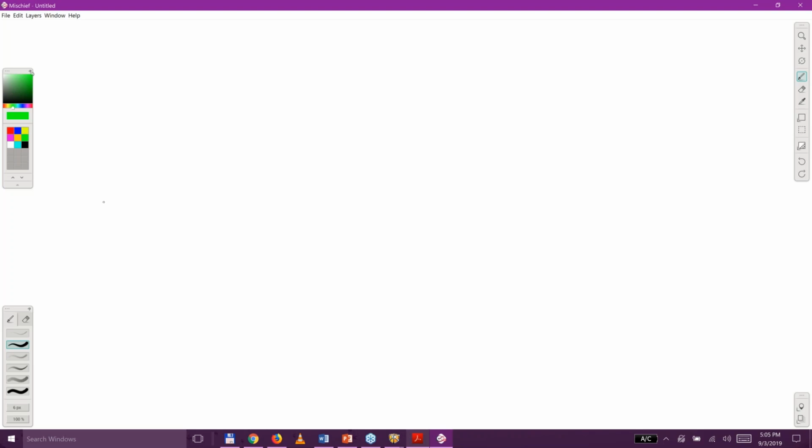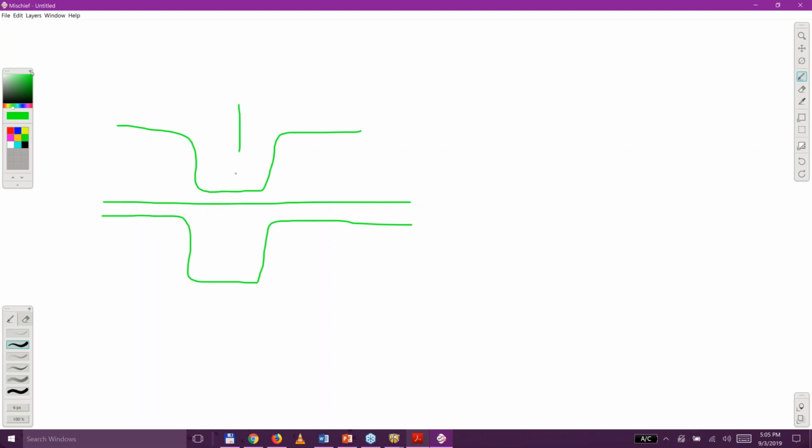If we talk about stamping, you've got a sheet of metal there, and you have a punch here, really poorly drawn punch, but I'm doing this with my mouse, and you have a die here. That punch comes down and pushes this into this shape in here, and then the punch retracts, and we need to be able to get the part out of there.